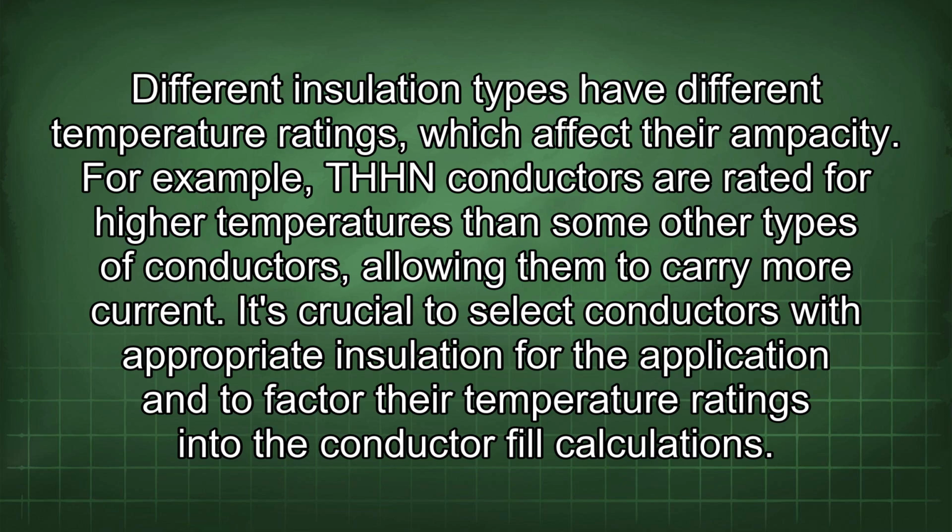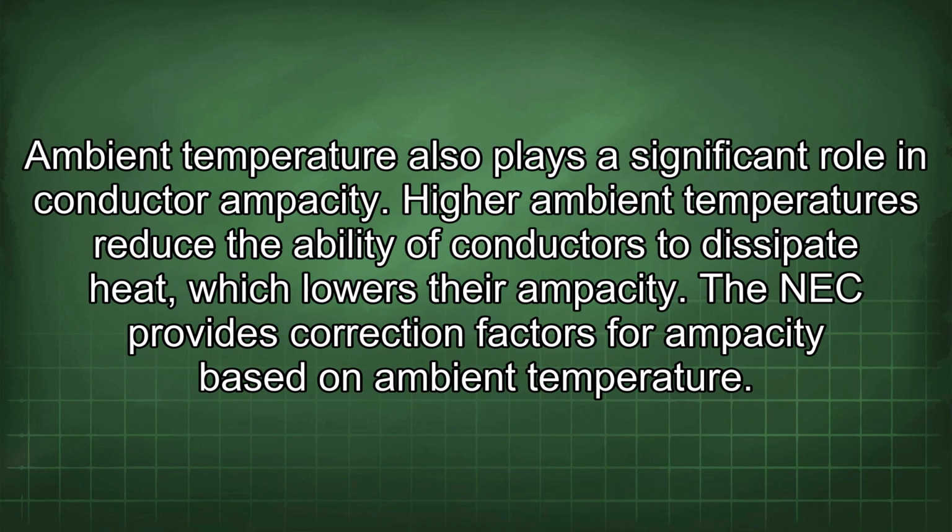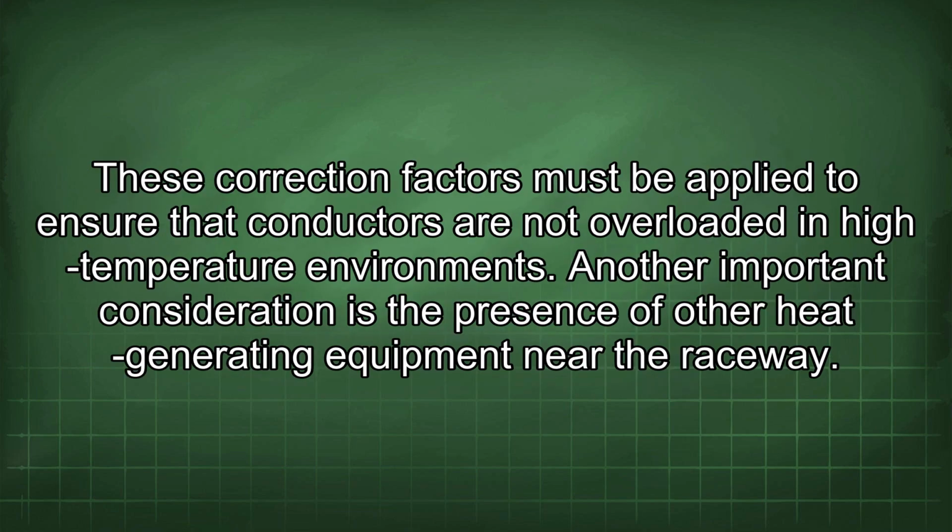conductor fill calculations. Ambient temperature also plays a significant role in conductor ampacity. Higher ambient temperatures reduce the ability of conductors to dissipate heat, which lowers their ampacity. The NEC provides correction factors for ampacity based on ambient temperature. These correction factors must be applied to ensure that conductors are not overloaded in high-temperature environments.